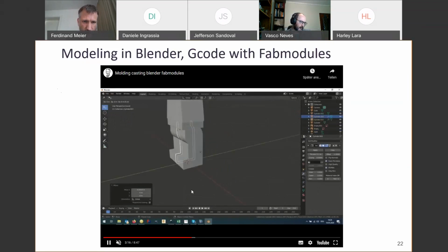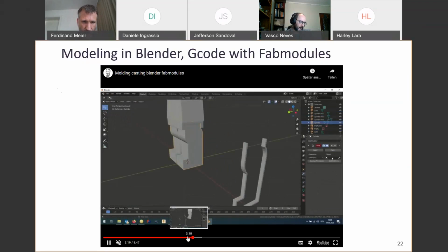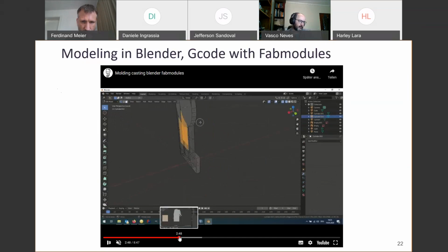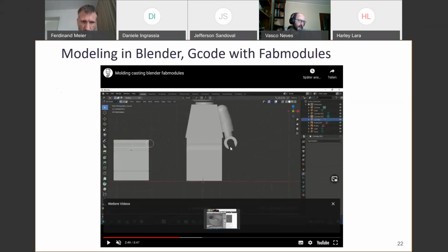And this again, like before making this hand, you should know very well how deep your 3 mm end mill can go, because this has a certain height. And if your mill bumps to the sides, you will lose your model.